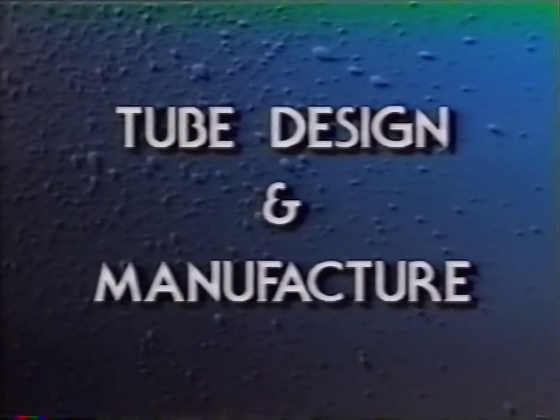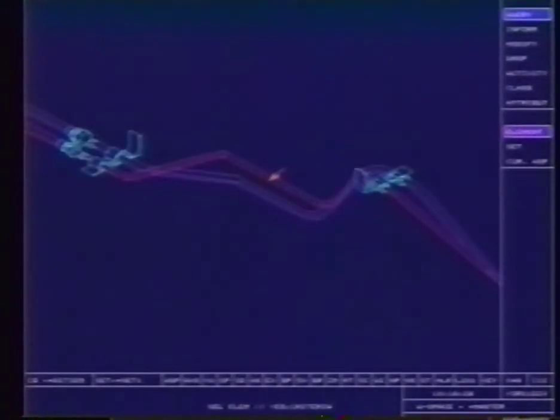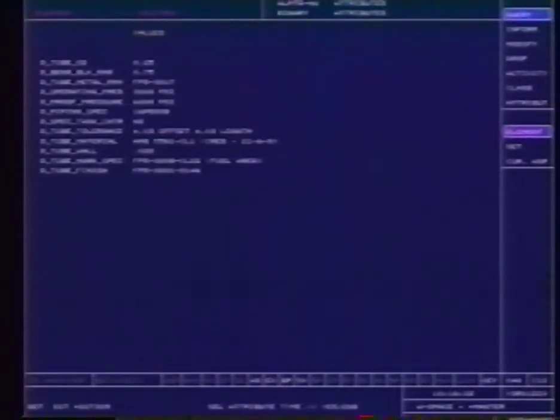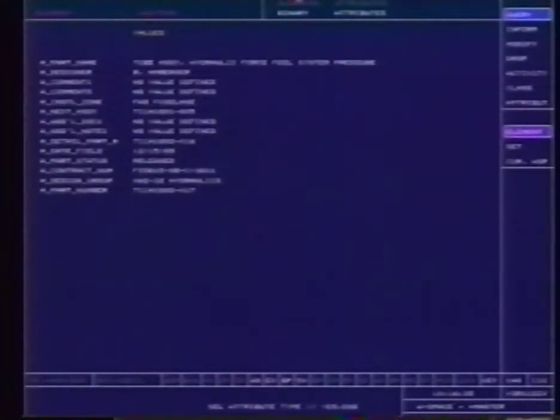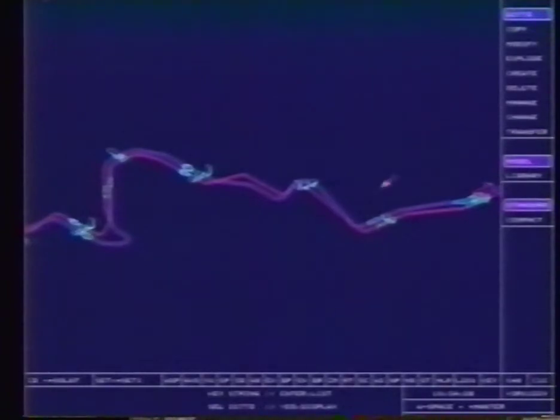Almost 90% of the hydraulic lines in the aircraft were either modified or of a new design. This resulted in the need to manufacture over 400 new hydraulic tubes. Tubes were modeled as solids defined by a center line which retains attribute information such as diameter, wall thickness, and material. A tube is designed so that it connects the appropriate hydraulic equipment with adequate clearance to existing equipment and structure.